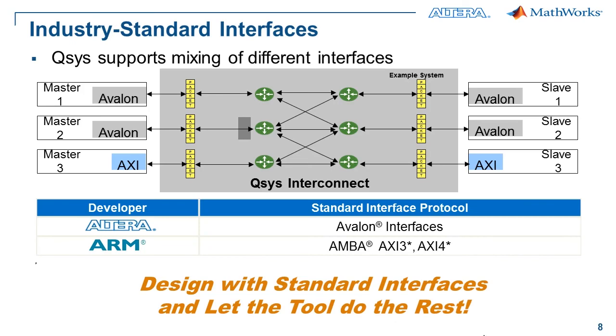Many IP cores use industry-standard interfaces for easier integration. However, it is unlikely that IP vendors, FPGA vendors, and FPGA designers like you all use the same industry-standard interface. So that's why Qsys uses an interconnect that supports mixing of different interfaces.